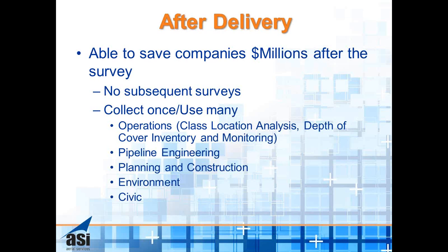I did a project, a 130-mile pipeline. We were able to collect using LiDAR, aerial photography, and ground survey for ground truth verification, for a cost somewhere between $300,000 and $500,000. We're delivering in 6 to 9 weeks. Ground survey would have cost about $1.1 to $1.2 million and would have taken about 20 weeks. So I'm delivering 13 weeks faster at a significant savings to the customer.